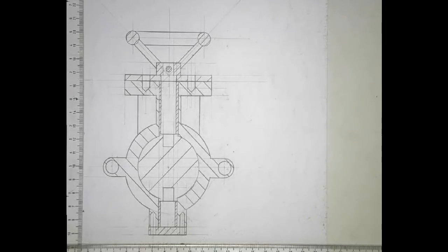First priority is to make sure that all of your components are drawn correctly, to the correct proportions, to the correct dimensions. Second priority is to ensure that they're all indicated in the correct place. Remember, it's more important to draw a component completely than have parts of the component represented. So rather complete one component entirely than present 2 half-drawn components. And then with the sectioning, keep it as neat as possible and remember the components that should and should not be sectioned.